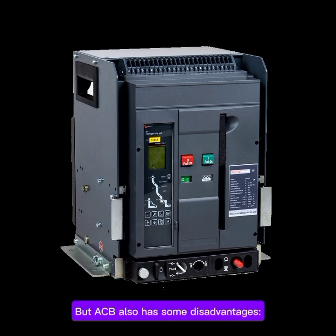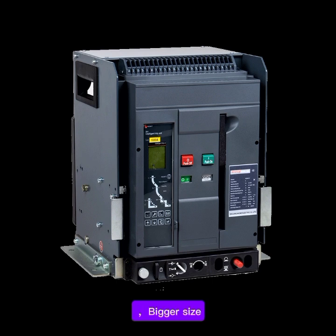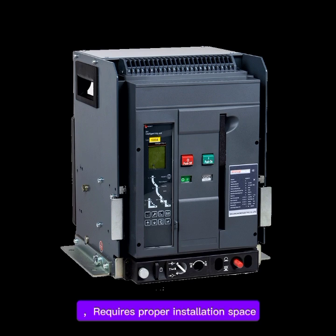Disadvantages of ACB. But ACB also has some disadvantages. Expensive compared to MCCB. Bigger size. Requires proper installation space. Maintenance is necessary for smooth operation. Common ACB problems. Some common ACB problems are ACB not closing, spring charging failure, trip unit error, overheating at terminals, contact burning, arc chute damage, loose busbar connection, mechanical interlock failure.